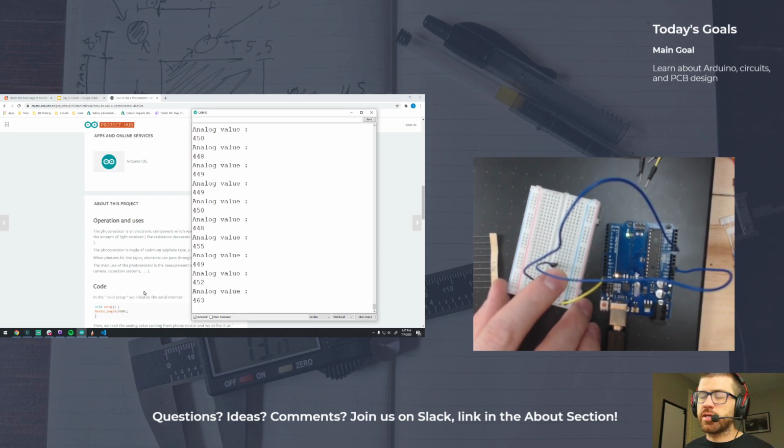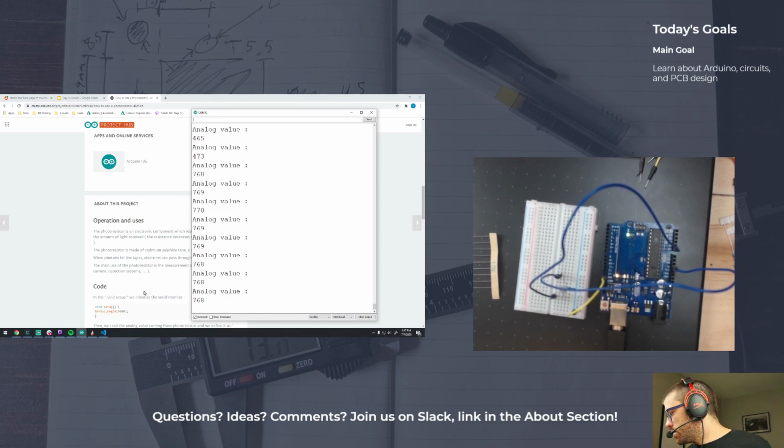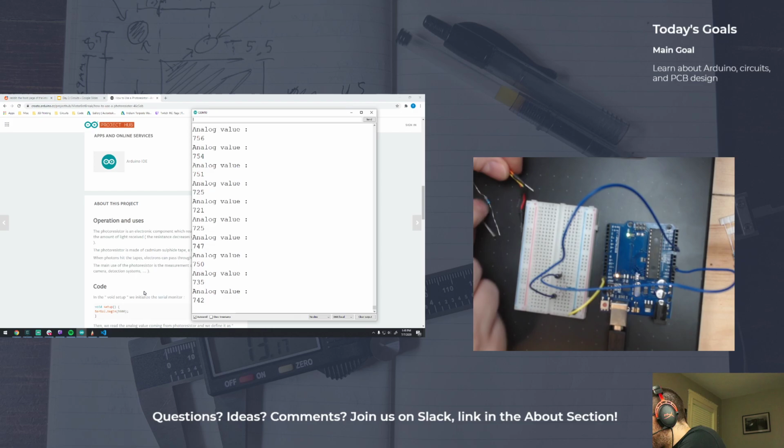So we'll use some LEDs for nightlights. We have what we just constructed with our LEDs before, and we could use that same code, that same idea, merge it together with this code, and we can get ourselves an LED nightlight. We recall that for LEDs to work, we need 220 resistors. So I will grab a 220 resistor. I will grab a blue LED. And we'll need some wires. So bring our wires back in.